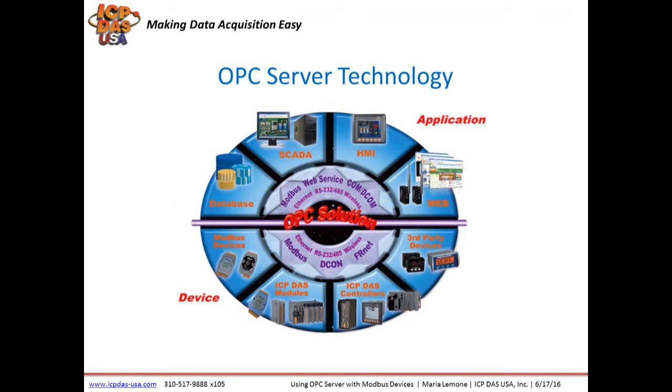OPC Server is OLE, Object Linking and Embedding, for process control, which allows Windows-based software programs to communicate with industrial hardware equipment like PLCs, PACs, and I/O. OPC is an open standard and supports many different vendors' devices. OPC supports server and client connections.